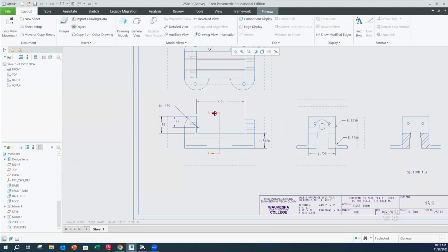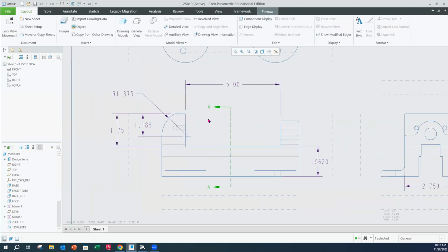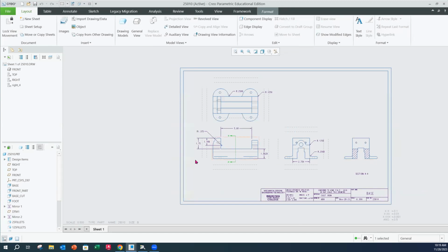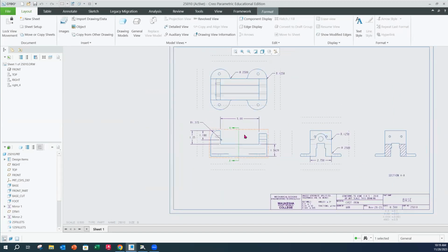Okay. You cannot have them go down below the surface because, remember, this is the view, we're looking in this direction and those arrows are always going to be pointing away from our section view. They place them in the correct orientation, so don't be moving those around, but they have to be taller than the highest and lower than the lowest extents of our view because that's what's being included here. Okay. All right, so that's our section AA. So make sure that those are in place. Don't forget your arrows because we'll be looking for those.